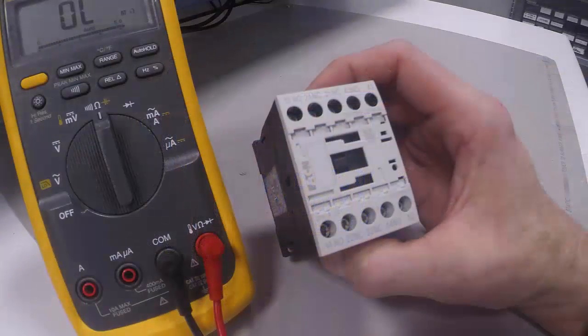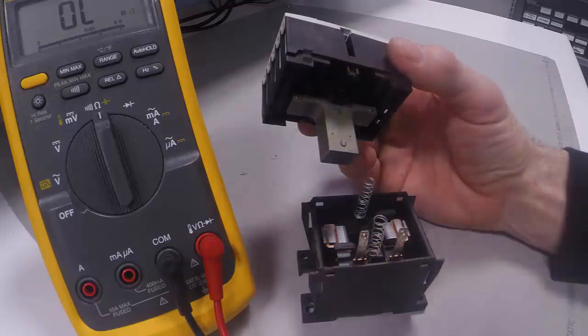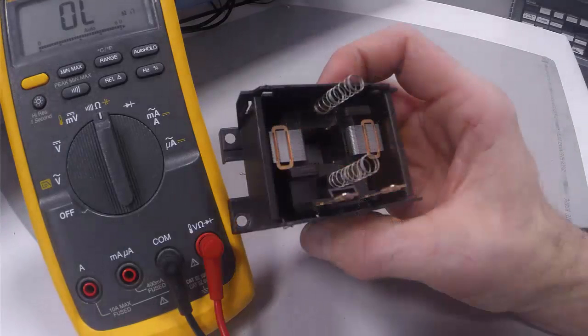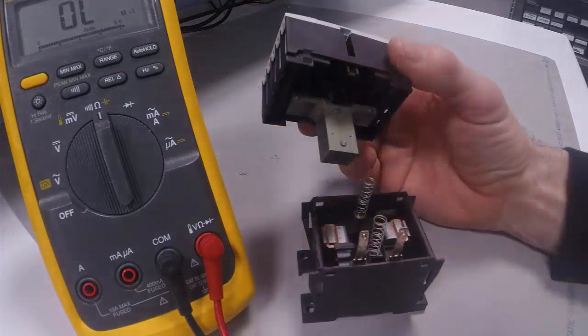One must disassemble a mini contactor relay to see the coil and armature. Upon cracking it open, we see something similar to the internal workings of a contactor. The base carries the stationary portion of the solenoid, the coil, and a pair of return springs that are maddeningly hard to properly realign when you reassemble the relay. Notice the shading ring. The coil is meant to be energized by 120 volts AC. The inductively linked shade ring keeps the armature engaged during zero crossing of the AC waveform and keeps audible hum to a minimum. The top portion contains the contacts, the contact carrier, and the armature.